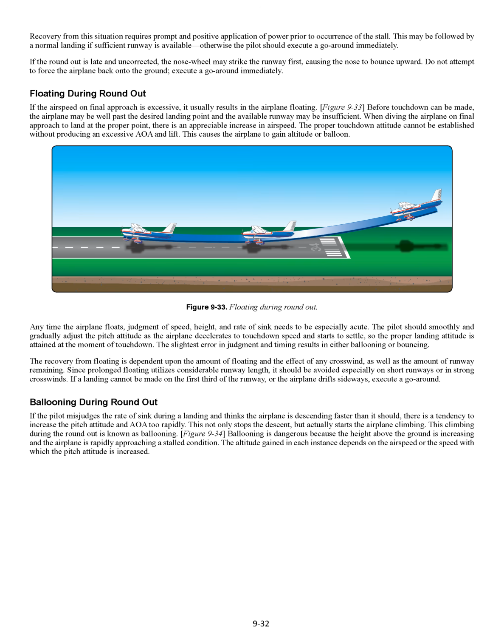The recovery from floating is dependent upon the amount of floating and the effect of any crosswind, as well as the amount of runway remaining. Since prolonged floating utilizes considerable runway length, it should be avoided especially on short runways or in strong crosswinds. If a landing cannot be made on the first third of the runway, or the airplane drifts sideways, execute a